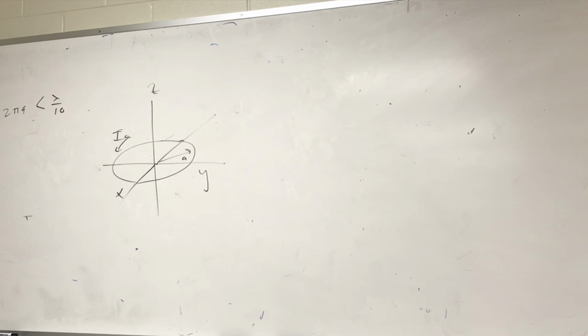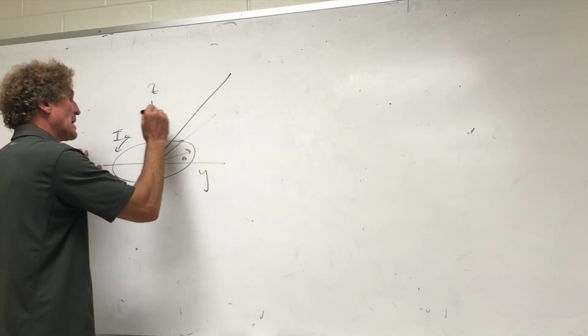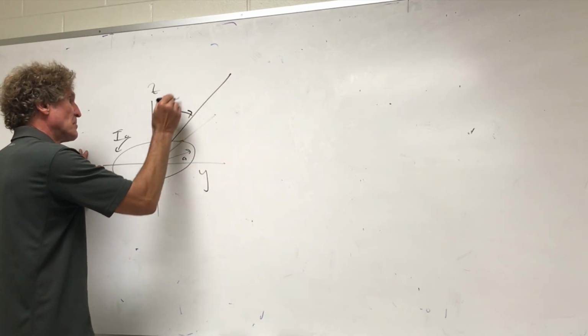You all with me? You said that's for far field? No, that's the definition of a small loop. Far field will always be for this one the same as the straight wire antenna. It'll be lambda over 2 pi. Always the same for these small antennas. So for this one, you're going to come out here, and here is the actual way it's done.